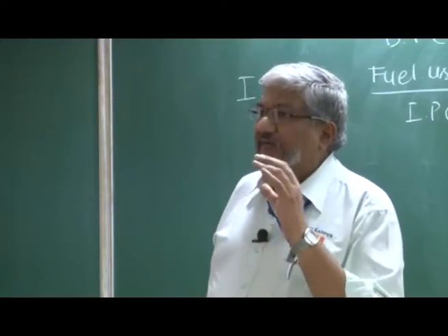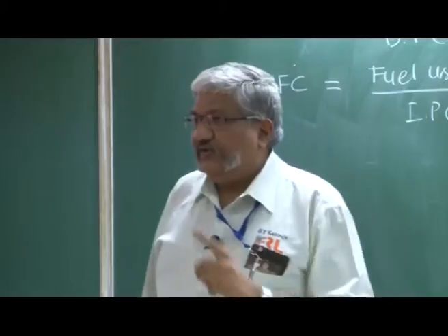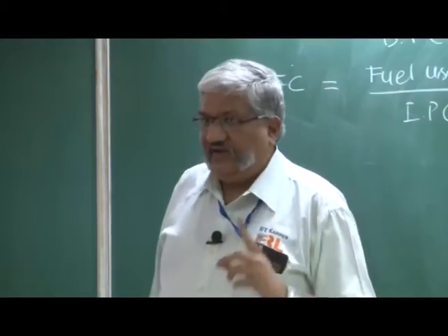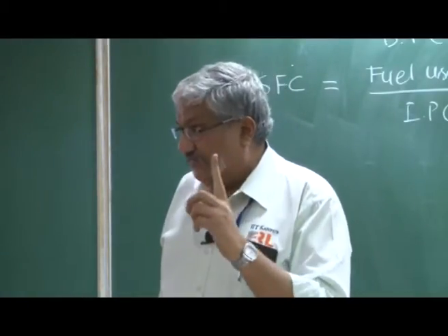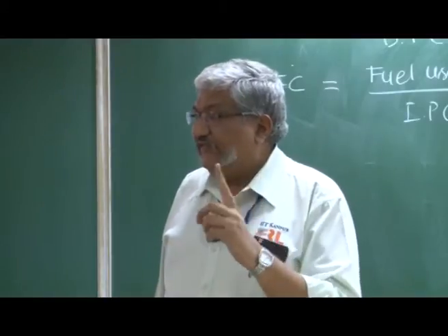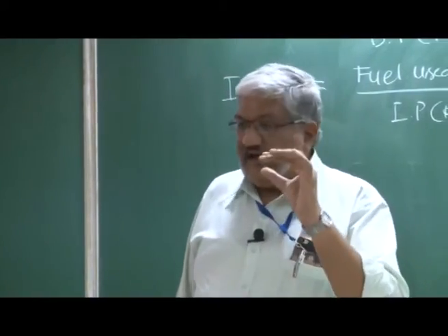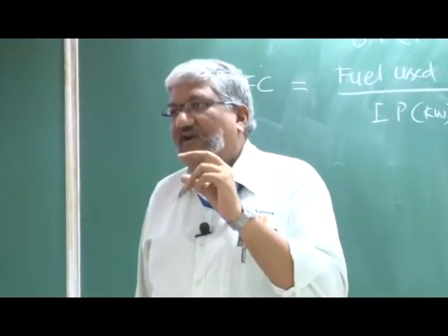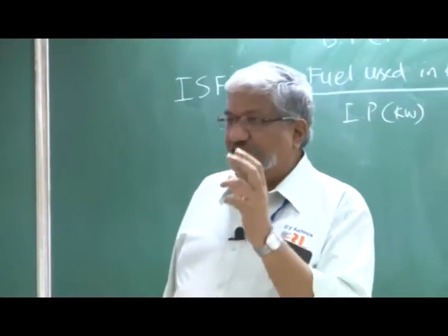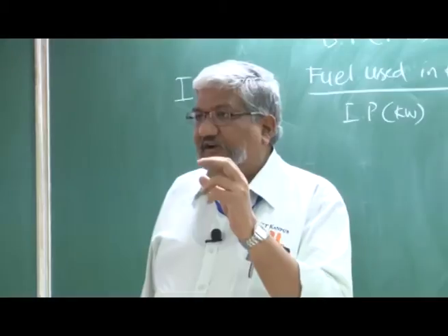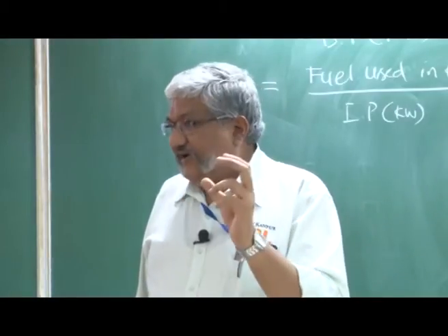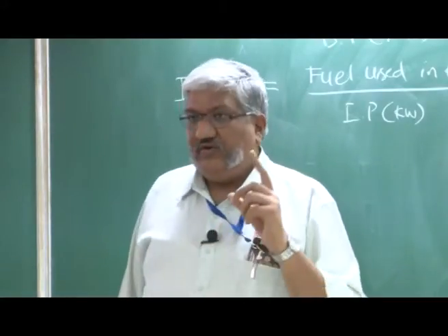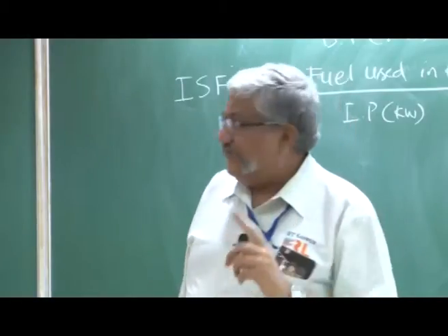What is more accurate is finding out the mass consumed, because please remember, when we say heating value, what is the unit? It's gram per kilowatt hour. It's gram, not milliliter. So certain mass has certain energy, but a certain volume does not have a fixed energy. The energy content of a particular volume of fuel will change depending on the ambient temperature. But the energy content of 1 gram of fuel will not depend on the temperature. At 45 degrees it will have the same value, at 15 degrees also the same value. So measurement of the mass is more reliable.